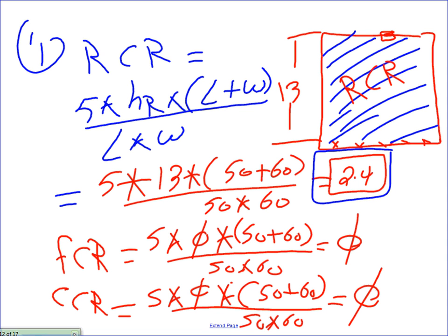Any questions about this? Straightforward. Now, actually, if I don't tell you that the height of the room cavity is 13, you wouldn't be able to do it. On the test tomorrow, I will tell you that the height of the room cavity is 13, and the height of the room is 13. So what would that give you? Meaning the height of the ceiling cavity is big fat 0, and the height of the floor cavity is big fat 0. Any questions about this? We do this in hallways where we need the light to be right at the floor level.